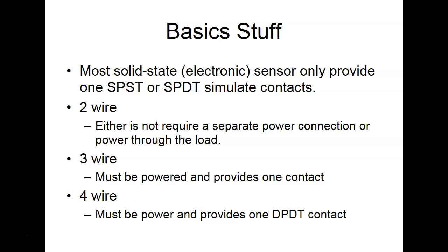But you're not going to hear a click like we do on relays, right? You're not going to hear that click that tells you that it's operating. A lot of them will put a little LED on the side, which is pretty neat. That'll light up when it triggers and allows something to come through. What we have to realize is these guys will always drop a voltage across them, because they're not real contacts, they're electronic devices.